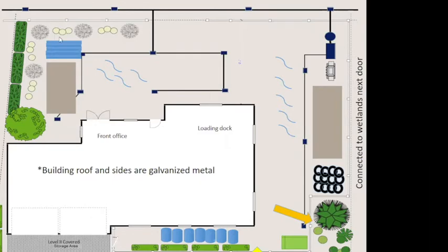Okay, good. And I think finally, you've got alligator pavement, you'd probably want to do the same thing. Now, one of the things about using permeable pavement is that sometimes it doesn't stand up to a lot of truck traffic.